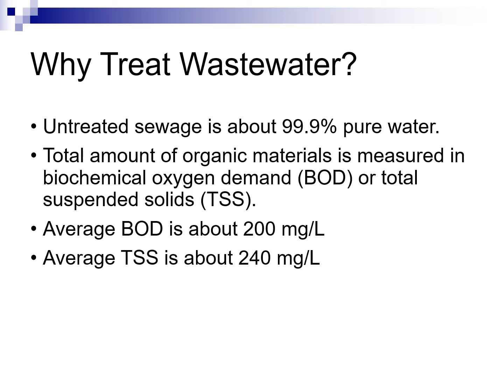So the total amount of organic materials is measured in biochemical oxygen demand or total suspended solids. Average biochemical oxygen demand is about 200 milligrams per liter, and the average total suspended solids is about 240 milligrams per liter.